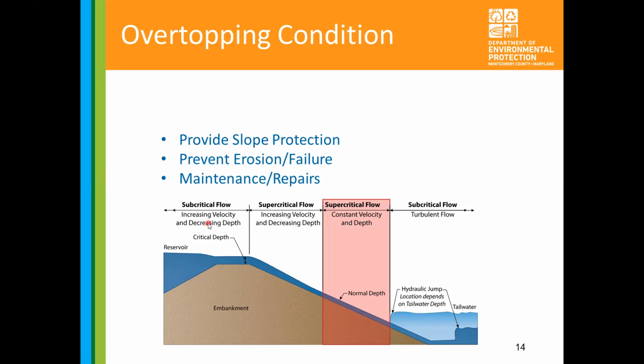So just a quick synopsis on the difference between subcritical and supercritical flow. I'm sure you've all seen in a stream where the water is flowing deep and slow, and then it hits a rock or something similar, and then it goes really shallow and really fast, almost like rapids. So you can see it goes slow and deep, hits the surface, gets narrow and fast, and then as you see in rocks and streams, it hits the bottom there, and it does almost like a swirl, and that's it transitioning back, the turbulent flow. A lot of times that's a hydraulic jump, for terminology for future slides.